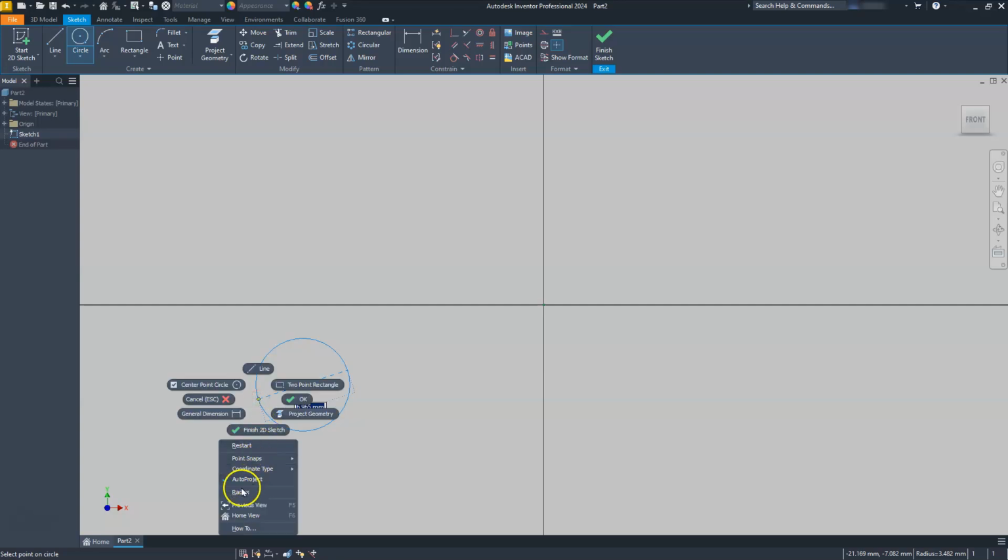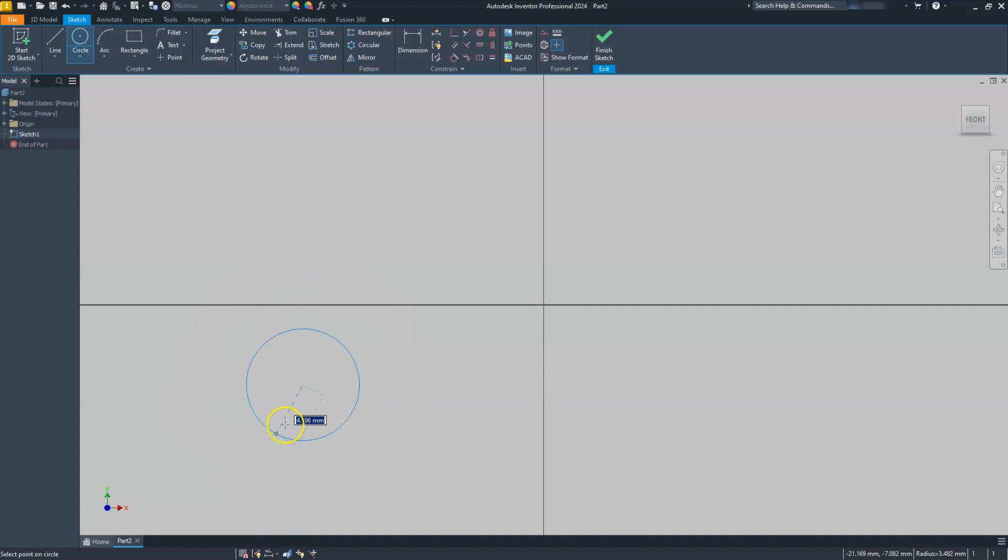So do a right click, and then I can choose radius. And you can see the difference now that that dotted line is only going from the center to any edge on my circle here. Now the length of that is my small radius, right? Remember I created one that was called small radius. So I'm just going to type in SM underscore RAD. And you can see that it's not red anymore. If it does create that and keep that parameter and it turns black, that means that it can find that. So once I hit enter, by default, it should put that small radius there.